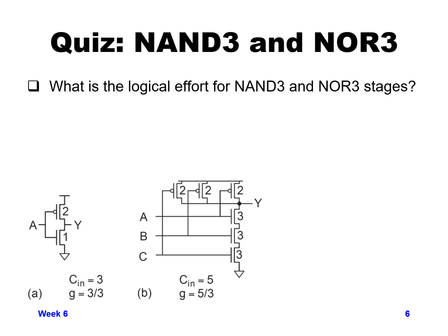function. In order to get the appropriate drive strength for the PMOS devices, since those are in parallel, they stay the same size as the base unit inverter, so they're all size 2. The NMOS devices in series, since we have 3 in series with each other, the net drive strength will be 1/3 of what it used to be, because we have 3 resistances effectively in series with each other, so 3 times the resistance.